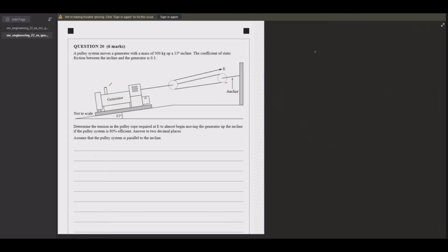So, in this question, while we do have 2 active wires, we have to look a bit more closely with this system here. Let's first define active and inactive wires. Active wires are the ones that support the load. And they do this when they're connected to pulleys and the load, or another load connecting pulley, but on both sides. So this wire here, because it's free on one end and we're pulling it, that is an inactive wire. And generally, for most simple pulley systems, we can just count the number of active wires, and that's going to give us the velocity ratio, but not in this case.